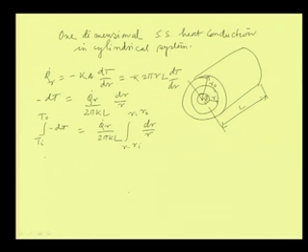If we do the analysis now, we will get T I minus T O, because of the negative sign I have changed the integration limits from T O to T I. So, T I minus T O will be equal to Q dot R by twice pi k L into ln R O by R I. So, this becomes the temperature expression.